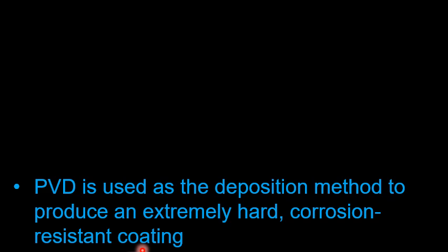The plasma has very high energy, and when the high energetic plasma, which is basically produced from a source material, is transported and interacts on the surface of the substrate, it has a serious interaction with the surface. And that's the reason, due to the higher energy of the plasma produced inside the reaction chamber, it results in a very hard coating, a very hard interaction of the plasma of the source material with the substrate.